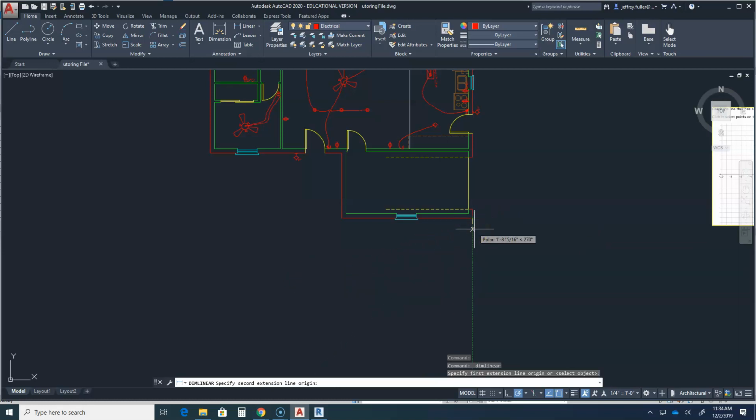So I'm going to start over here on the right, because that is the part of the house that extends furthest, and that's where I want to measure my 8 feet of distance from. Okay, and just kind of reference that geometry over there. Now, because I'm pulling this dimension line downward away from the house, I'm actually going in the y-axis direction. I'm not going anywhere in the x-axis direction.